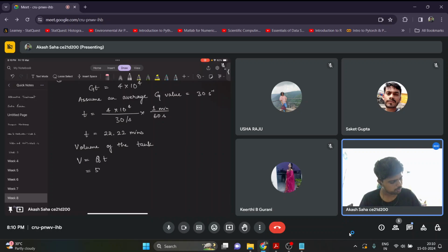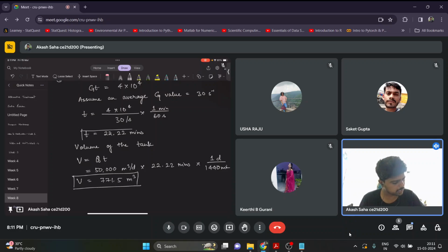So flow rate I know: 50,000 meter cube per day into 22 minutes. Since the flow rate is in days, I will write 1 day by 1440 minutes. I'm just changing minutes into days. So whatever I get, I get V as 771.5 meter cube. So this is my volume. So I got the time, I got the volume also.